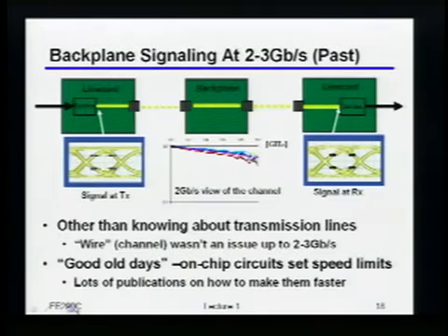Okay? Okay, so now I think we're going to finally get back to Ricky and Linkai's questions from before. So as I said before, conceptually, that very basic picture of just having some flops and an inverter, again, it's not exactly right, but conceptually it actually turned out to work reasonably well up until relatively recently. Other than the fact that the wires were actually transmission lines because of the speed of light, which drove a few changes in how people built the links, up to about 2 to 3 gigabits per second or so, life was actually pretty good for link designers.